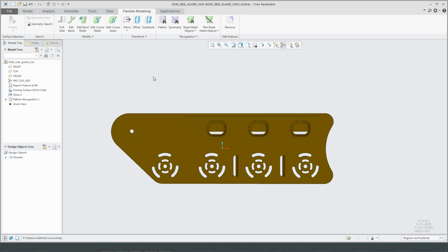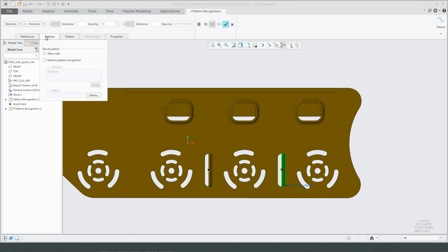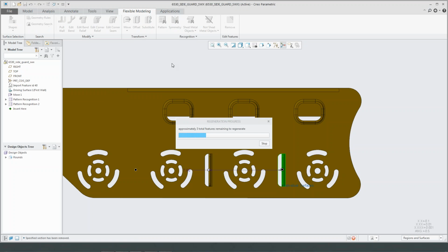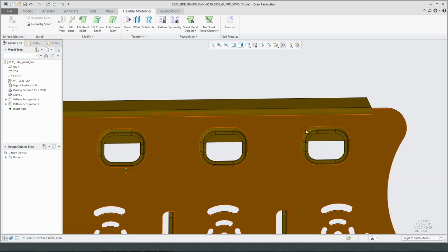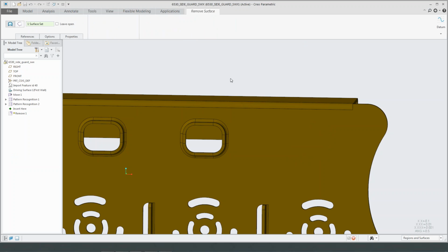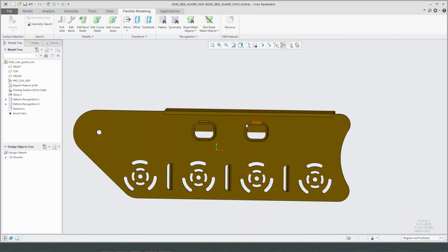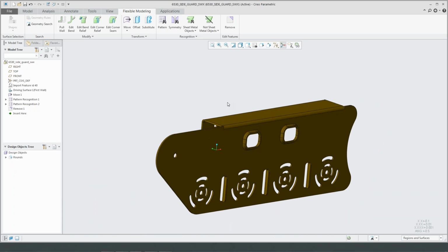So now I'm manipulating the geometry for a current design. I could do that as well to this other aspect here, this cutout. I can say, you know, let's keep that consistent as well. And maybe we don't really need some of these features too. So this guy back here, maybe I just need 2 of those so I can remove one and defeature that down. So that's kind of how flexible modeling works.